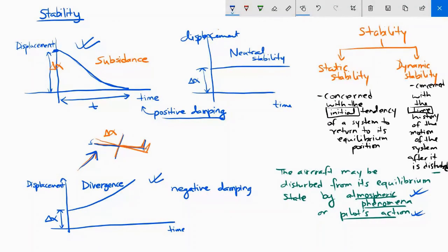Okay, so in such system, if you have ended up designing such a system which is characterized by negative damping, then you may want to introduce some artificial damping into the system so that it can be brought back into equilibrium. Okay, so again, these things will be more important when we actually write some equations and we calculate the damping ratios. So their values being positive or negative is going to imply whether the system is dynamically stable or not.